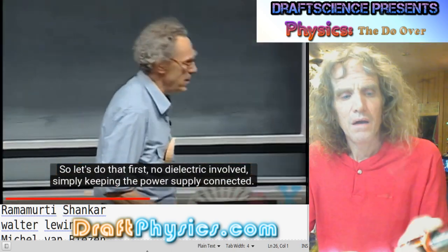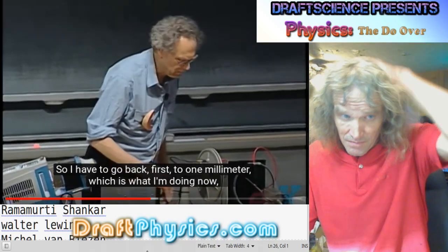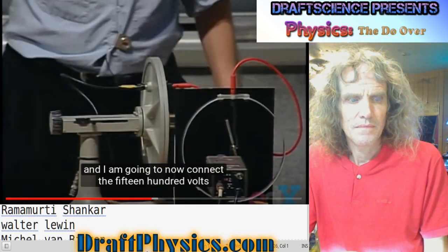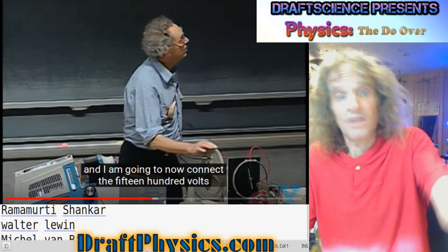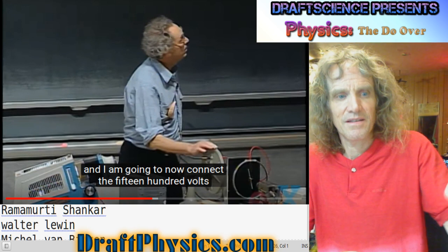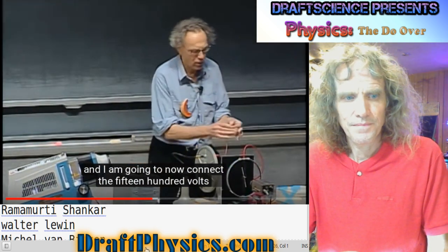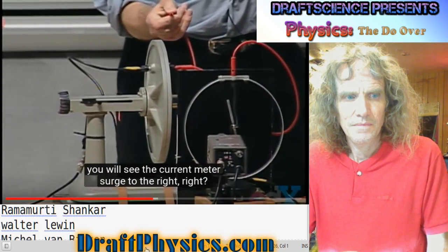No dielectric involved. Simply keeping the power supply connected. So I have to go back first to 1 millimeter, which is what I'm doing now. I have here this thin sheet to make sure that I don't short them out. It's about 1 millimeter. It would be interesting if you shove the thin sheet in while it has a 7 millimeter separation, and then shove this thin separation in and see what kind of change that creates. Now connect 1500 volts and keep it on. And as I charge it, you will see the current meter surge to the right.